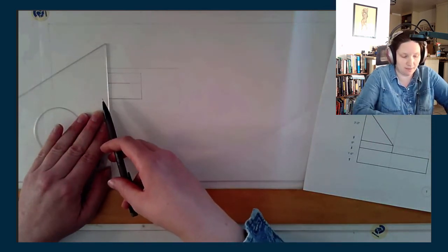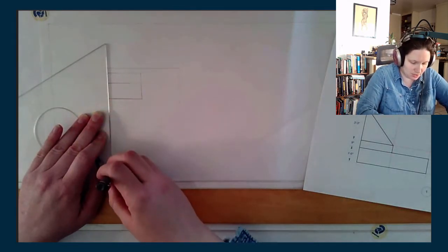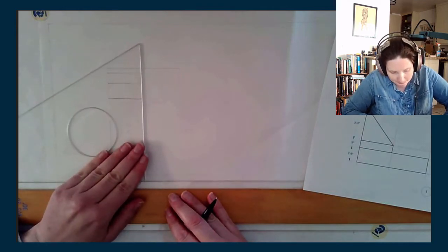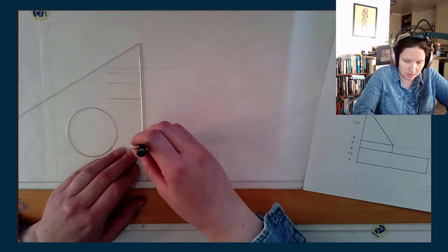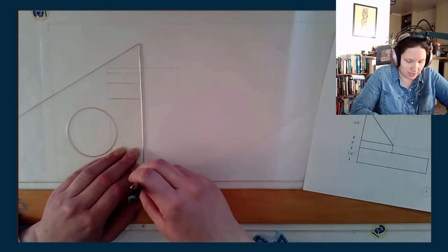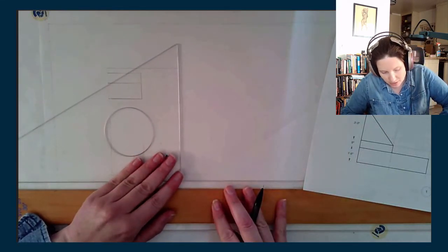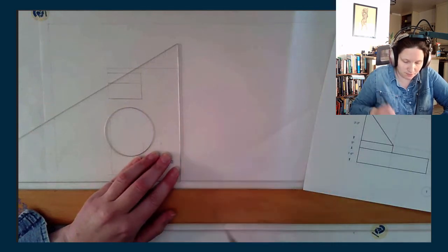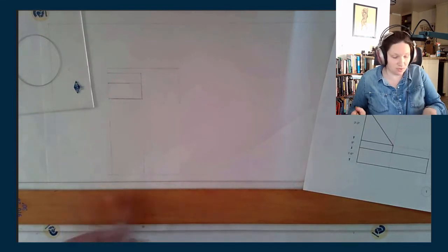We have the top view as our guide, okay? So I'm just going to bring this down, lining it up with each of these existing lines. And I kind of have an idea in my head of how tall I need. I'll have extra height, more than I need on this plate, and that's a good thing. So this, I don't need it to be as tall, right? I know it's only 1'6". Okay. So now I have these 3 lines.